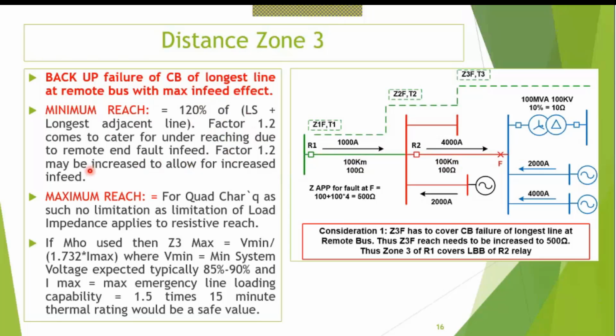I have in one slide, not today, in the next session, I'll show a complicated setting example where this was set to around 150, 160% of this longest line, because the fault infeed at the remote bus was so high.